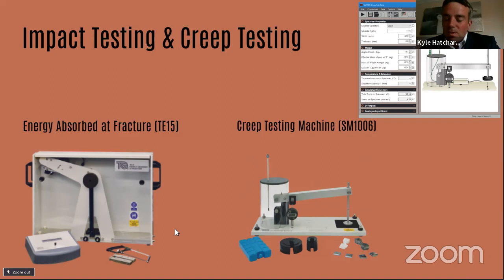So then we move on to the energy absorbed at fracture. This is all about understanding the point at which crack propagation occurs and the energy that it takes. So it's not about crack initiation. What I mean by that is that you have a test piece of material, you slot it in between the 2 circles at the bottom of that particular apparatus. There's a swinging arm that you rotate 90 degrees to the right with the test piece in. You've created a notch, and the notch is to create a crack initiation, because if you didn't create that notch, you would be investigating the crack initiation, not the crack propagation. And it's crack propagation that you are interested in, the energy it takes on impact to fracture that material.